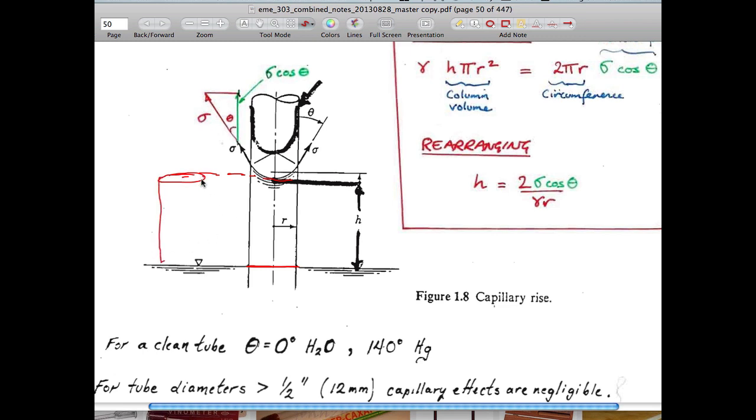a single tube of fluid, where the force balance that you want to do is a resolved force acting upwards, which I think is T, and a resolved force due to the weight acting downwards, which is going to be equivalent to the volume of that cylinder multiplied through by the unit weight. Of course, the unit weight is equal to the product of density and gravity, so this includes the planet we're on, for instance. And so we can evaluate what each of these components are.